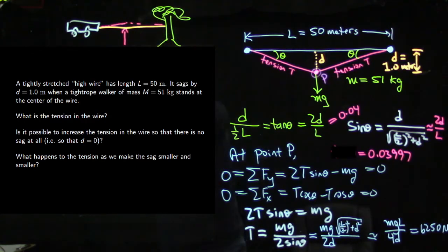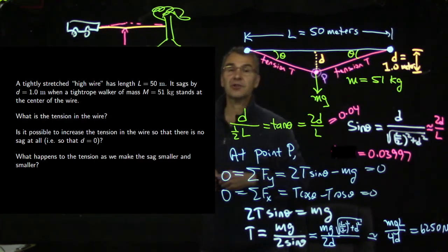So you could sit on the rope or you could push on the rope, but basically if you apply the biggest force you can in the middle of the rope, it makes a really small angle. So then the perpendicular force that you apply is multiplied by a big factor. That big factor is the reciprocal of the tangent of this tiny angle. So then the tension in the rope pulls on your car and might get your car out of the snow. I've never tried it. I look forward to trying it sometime.